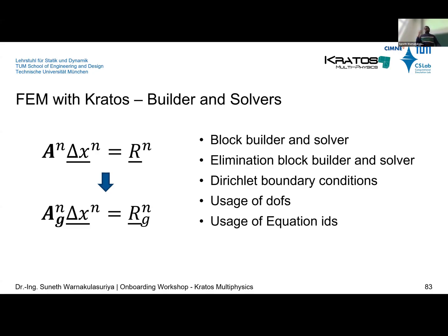Dirichlet boundary conditions you don't do specifically. You just pass it to the builder and solver, and it will automatically do it. Yeah, so it's using equation IDs to construct the global system matrix.